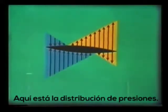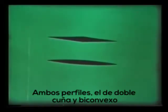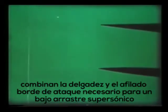Here's the pressure distribution. This area represents lift, which again acts at mid-chord. Here's a Schlieren wind tunnel picture. Both these aerofoils, double wedge and biconvex, combine the thinness and sharp leading edge needed for low supersonic wave drag with sufficient depth for structural strength.